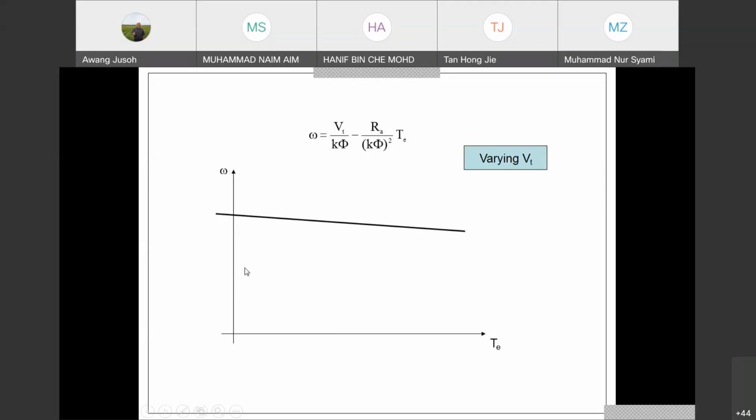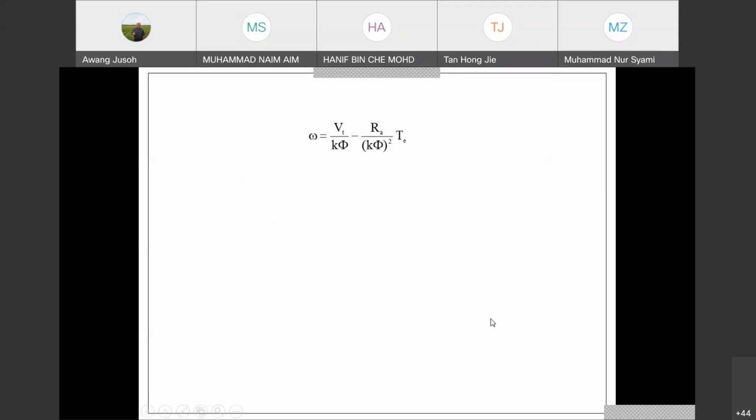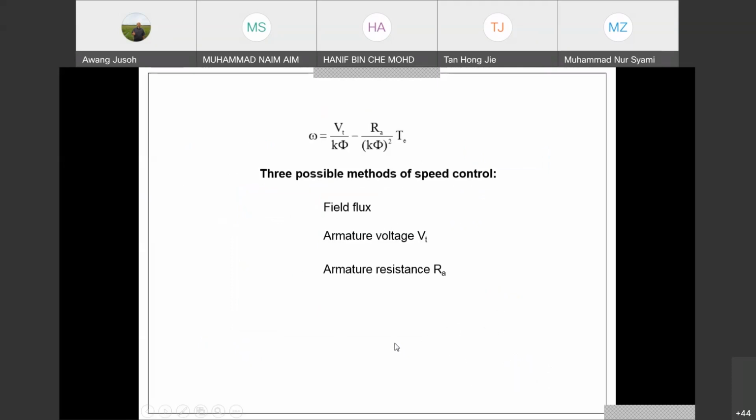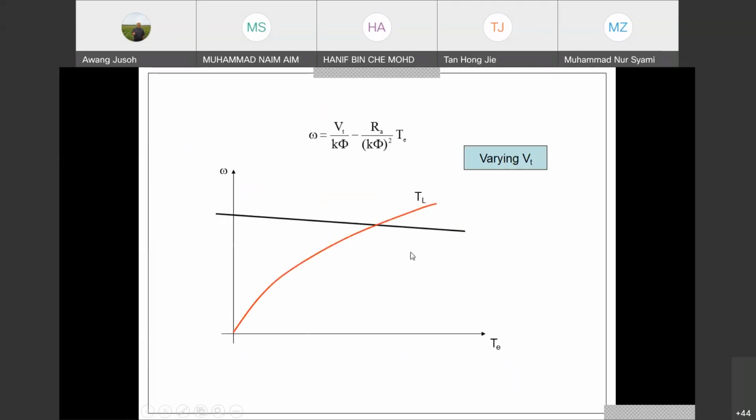When you increase torque or increase Ia, it is the same, because you have two formulas here relating Ia and torque. When you increase Ia or torque, what happens to the speed? The bigger the torque, the lower the speed. So you put a higher loading. Torque means loading. It is like your car.